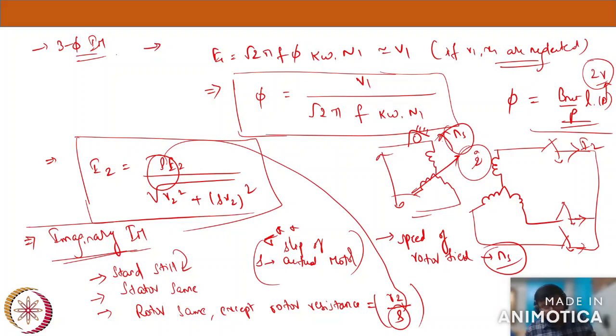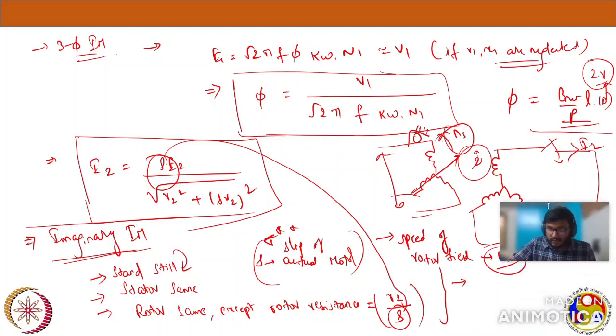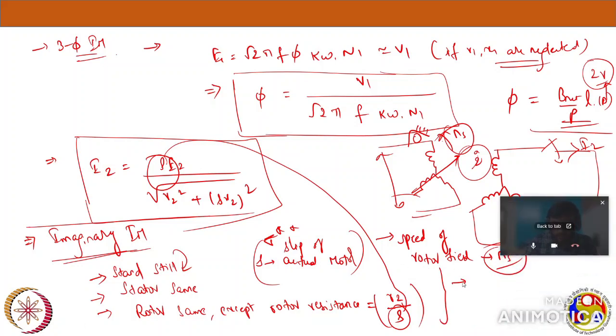So now I have my actual motor. I know the value of the slip there. I have taken that value of the slip, and I have calculated my new R2 by S resistance value, and I'm just writing the conditions here. Now in the secondary circuit, my rotor is standstill.